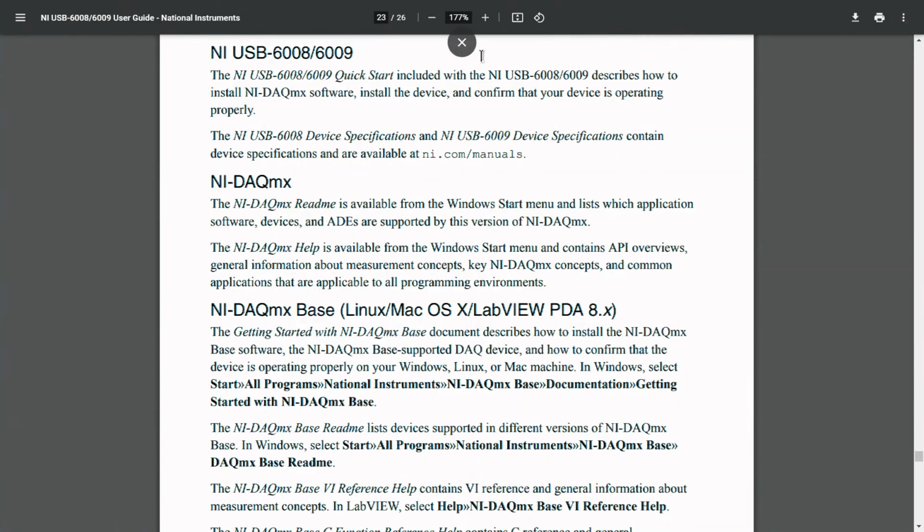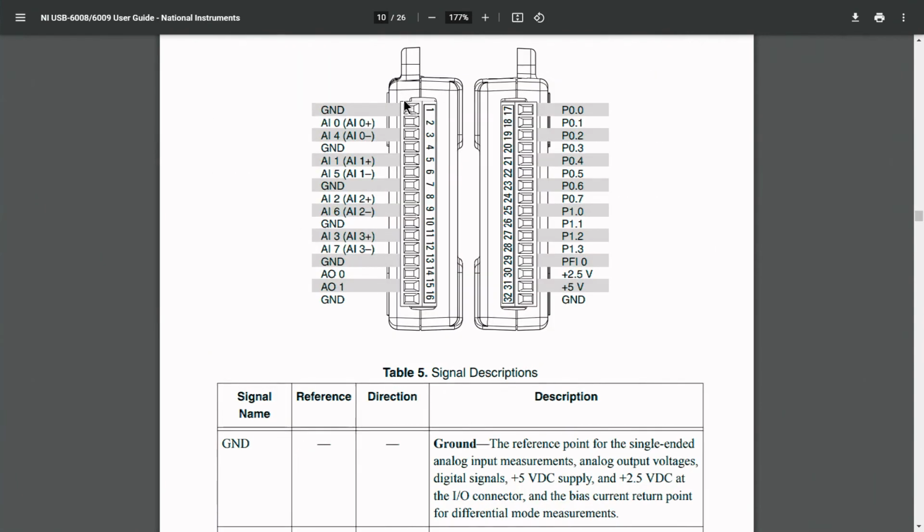Now we will see how to create a program in a lab environment in order to acquire the data using USB, and the configuration connections between input and output. Here I will use analog input 0, and the output will be connected to analog input 0, since the power required to power the LM35 temperature sensor can be taken from the DAQ.